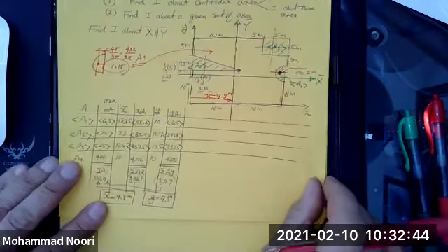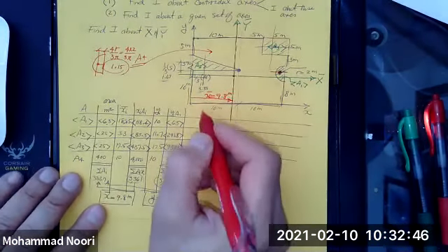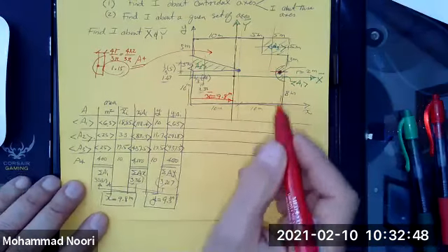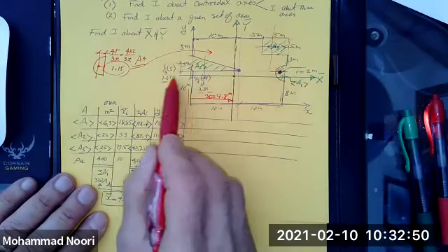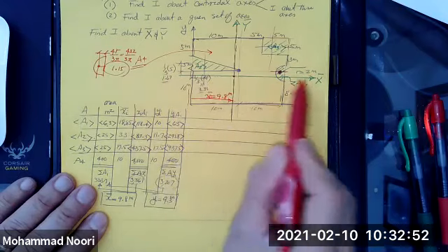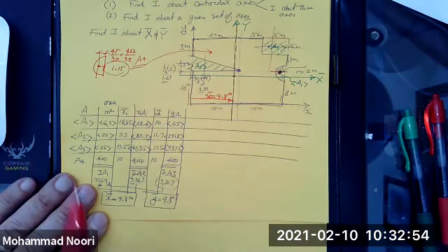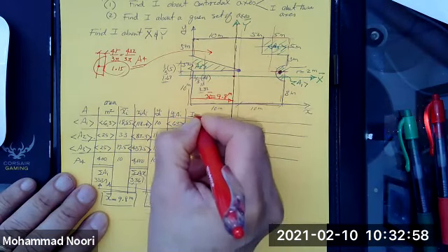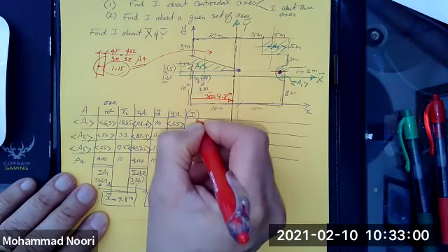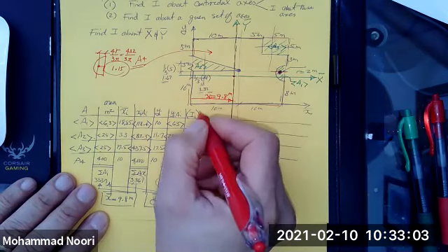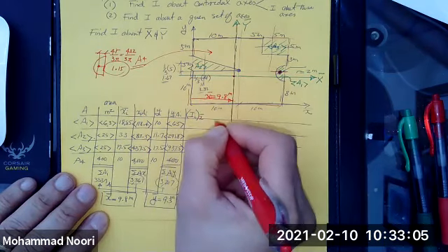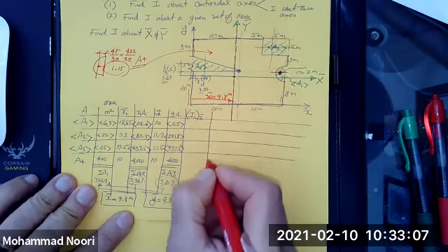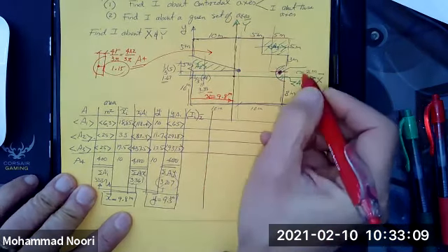As the first step, you just simply find the moment of inertia. Let's say you want to find the moment of inertia about this axis. So you set up a column, and in that column, you tabulate the moment of inertia of each shape about its own x centroidal axis.